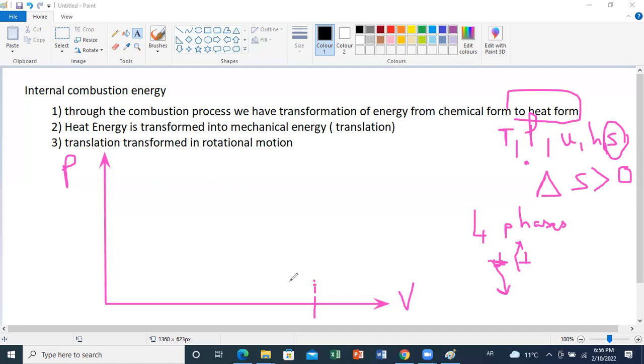and now I want to start to compress my mixture. Okay, because we said before combustion we should compress our mixture, and as the piston is moving upward, what will happen? The volume of air is decreasing, so you are compressing air inside your cylinder, and the pressure is increasing. So we can say that during compression we have this curve of decreasing volume and increase in pressure. So this curve here represents the compression stage.